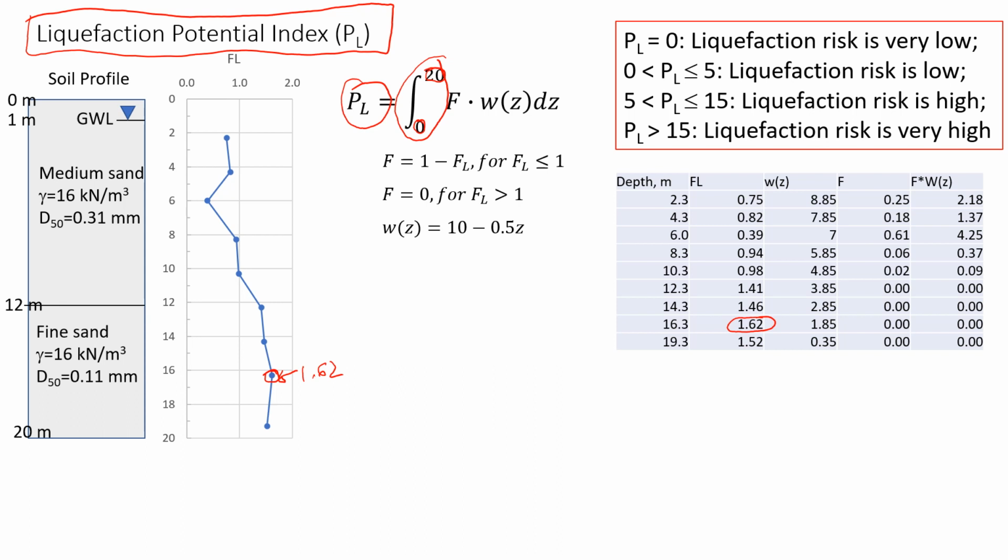It's because this procedure was developed for several cases that took place in Japan, and when they analyzed those cases, there was 20 meters of sandy, sometimes even silty material. So they came up with this procedure. They said, let's look at the first 20 meters, but it doesn't really matter, because whatever we're going to see, it's typically in the top few meters of the surface.